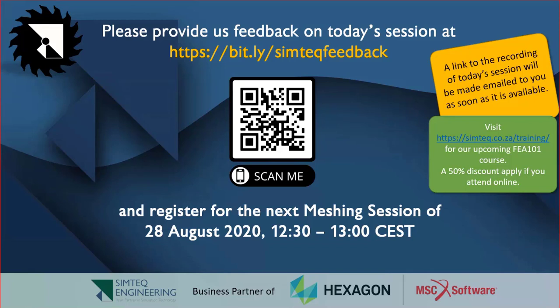If we extend that to the model where we extend those elements to the end, in that case there will be a little bit additional mass. So that will change that same approximation that I've used slightly, but because of the location where it is, that mass does not play a very large role. The mass at the end of the beam where it moves the most is the most important in that kind of a model. So in this specific case, I don't expect a much larger difference in eigenvalue than the square root of the difference in the displacement.